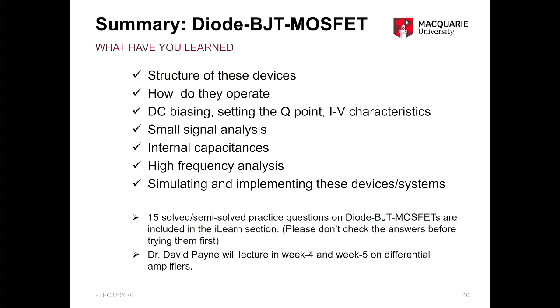You know what IV characteristics would look like, and you can find out what voltage would be at what current. We did some small signal analysis, tried to find internal capacitances, and from that did the high frequency analysis just by using the same techniques but adding the two capacitors in there.